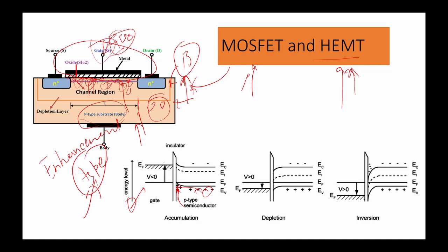So when charge is transported at the interface after the application of sufficient bias, the impurities will scatter these electrons, boron impurities. They will decrease the mobility of the electrons at this junction, so mobility of the electrons will be lesser in this case.